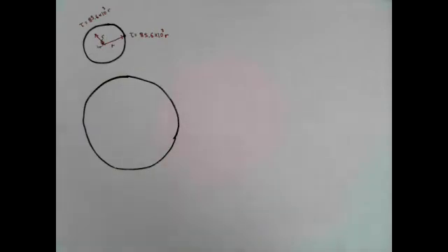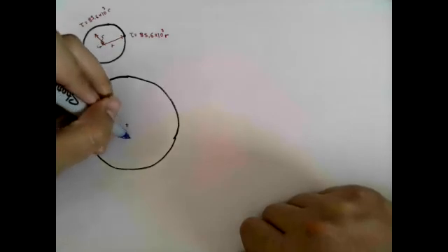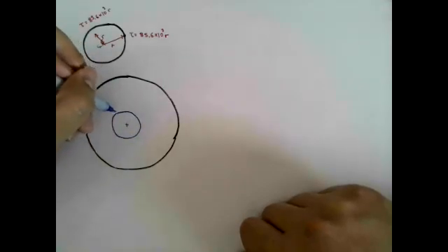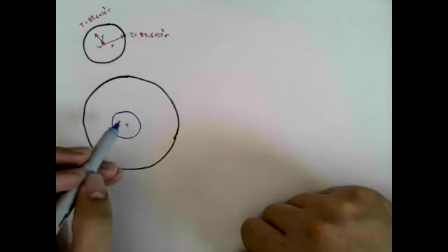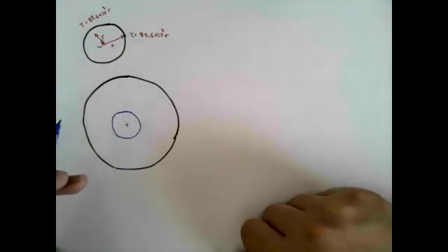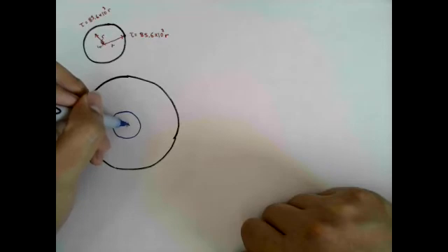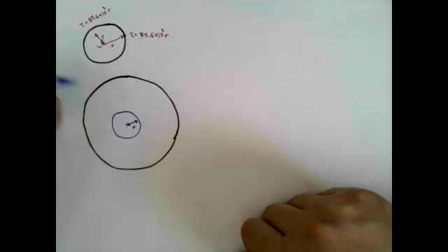So I'm going to take an infinitesimally small element. I know you've heard this before because I've done it for fluid statics, but when I say infinitesimally small, I mean a tiny, tiny, tiny element. This is my center, and I would like an element where the shear stress is constant all throughout. That means my element needs to be at a constant, consistent distance r from my center.